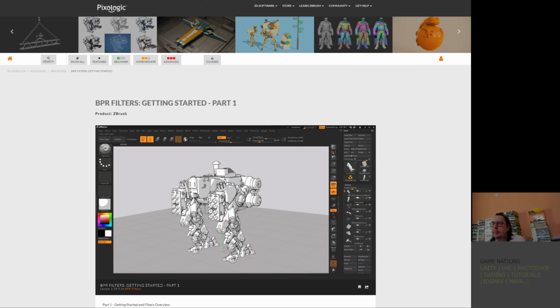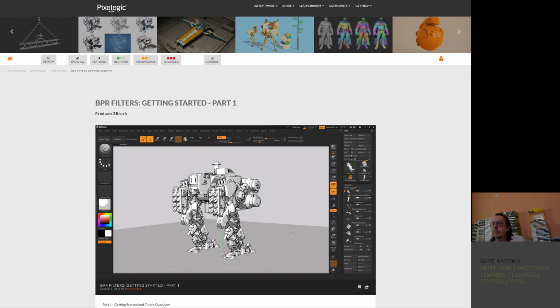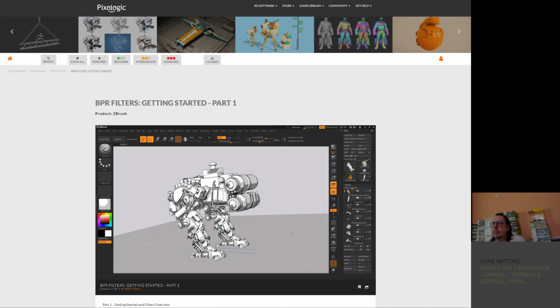Now at this stage, you may notice that some of the shadowing areas on the mesh here are still giving this kind of transitional gray value. So it's a blend of gray in certain areas. So I want to enable the flat preview shadows. So I'm going to go to the render palette up here and open this up. I'm going to navigate to the preview shadows area here, and I'm going to enable the flat shadow mode. And this will take the shadowing that's applied to the model, and instead of giving it a gradient value, it would actually render it as flat. And now with this active, you'll see now the model in real time here is looking something like this.